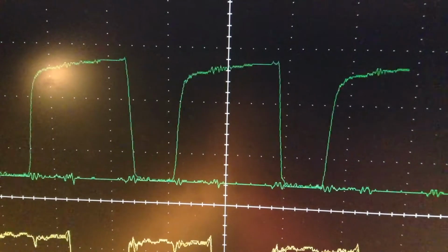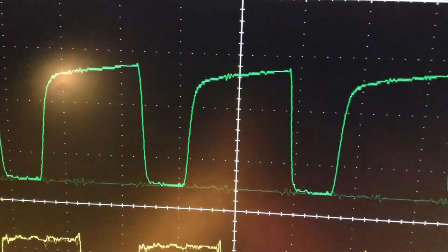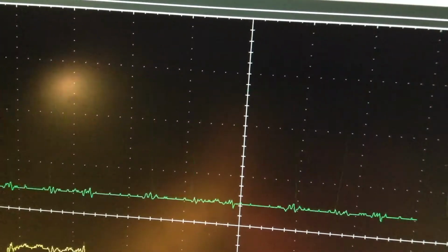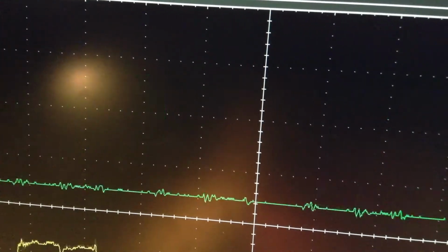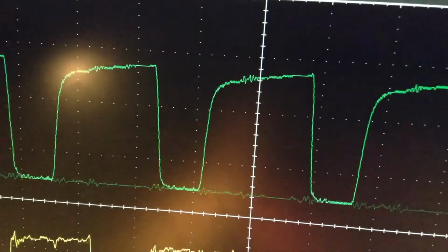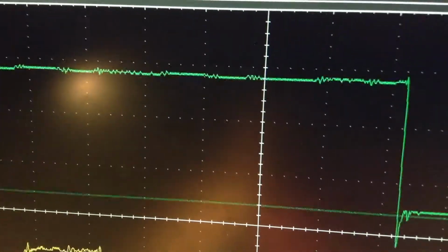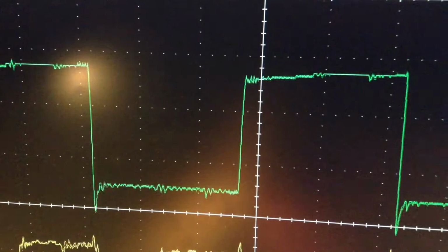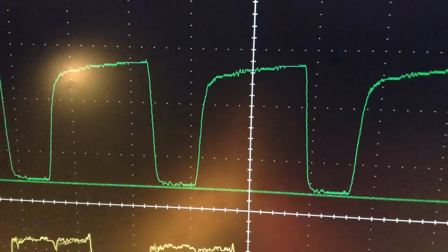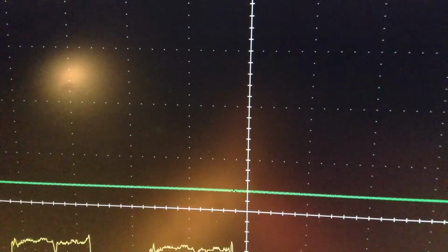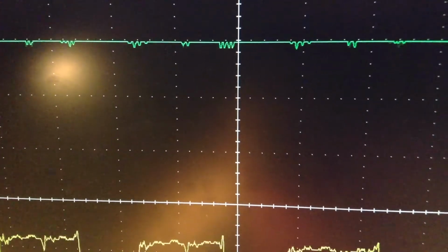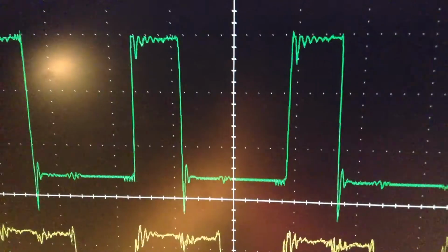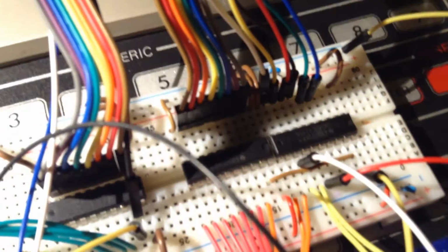And here is A10. And the reason for that is this is port pins, port 2 actually, of the Intel 8048. And these here are a completely different driver. So that's why. But anyway, when I connect on the other side of my bus transceiver, you can see that I square up a lot. So it's a bit noisy, but it works.